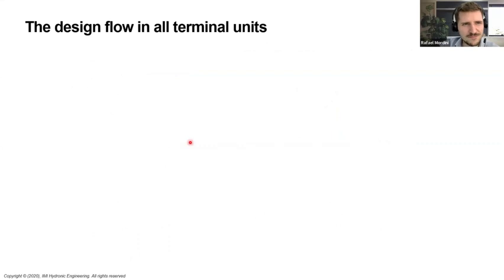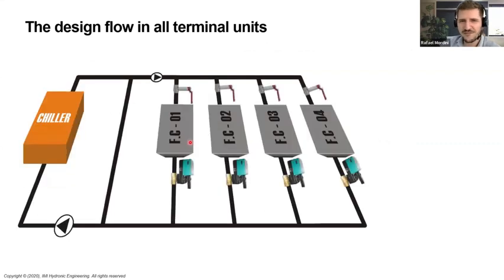Let's keep moving. Here, some math behind the balancing. Let's take a look at this example. We have here our primary pump that takes care of the chiller room. For this example, we don't care about what we have in the chiller room. We have here the decoupling bypass, right? And the secondary pump. This one is what matters to us. This pump is responsible for giving pressure for us to make the water flow through all those identical 4 circuits. We have some pressure drops here.